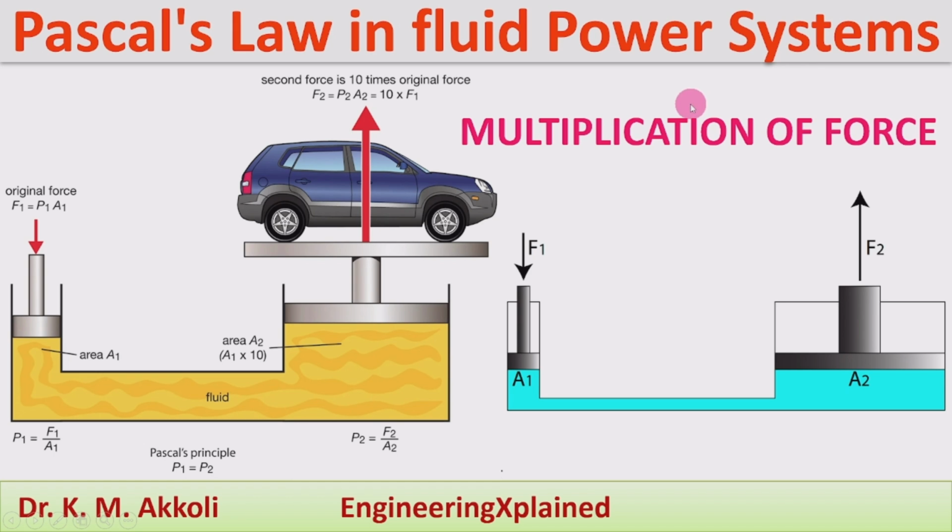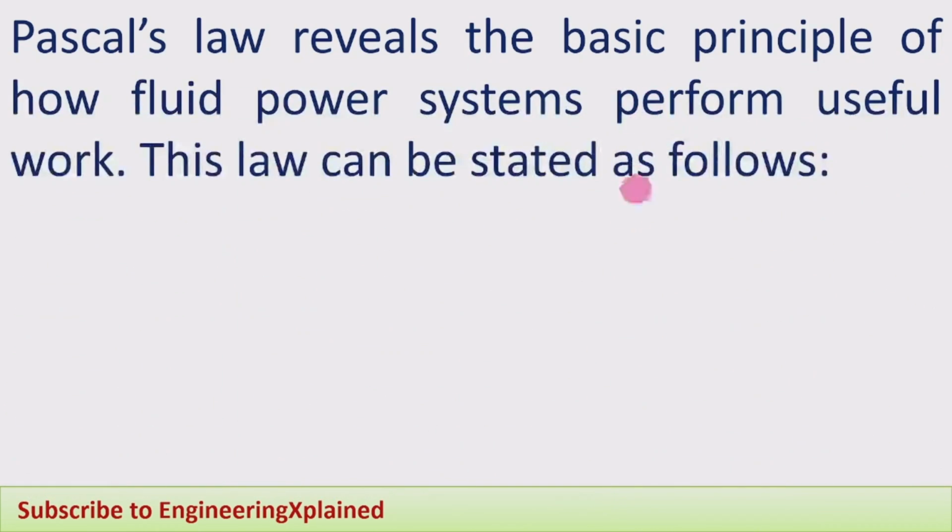Pascal's law, which is stated in fluid mechanics, and its modified form used in fluid power systems, is called the multiplication of forces. Here, the force is multiplied according to Pascal's law and the distribution of forces, and that I am going to explain here. Pascal's law reveals the basic principle of how fluid power systems perform useful work.